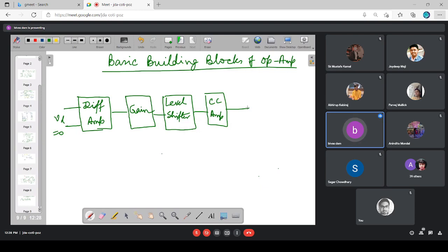So to account for this non-zero output voltage, we have no other way but to go for one assumption: one practical operational amplifier consisting of one ideal operational amplifier and one fixed piece of voltage source, which is termed the input offset voltage. Is this point clear?